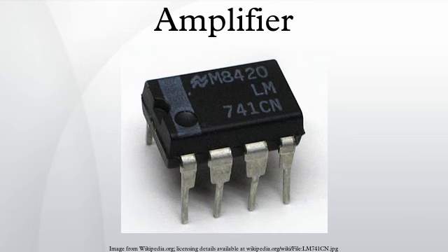Distributed amplifiers. These use transmission lines to temporarily split the signal and amplify each portion separately to achieve higher bandwidth than possible from a single amplifier. The outputs of each stage are combined in the output transmission line. This type of amplifier was commonly used on oscilloscopes as the final vertical amplifier. The transmission lines were often housed inside the display tube glass envelope.